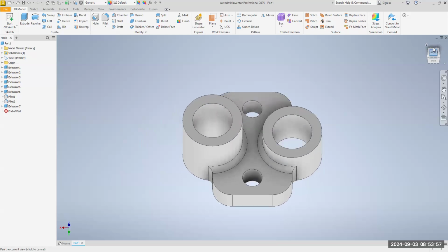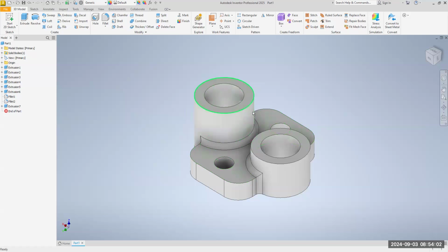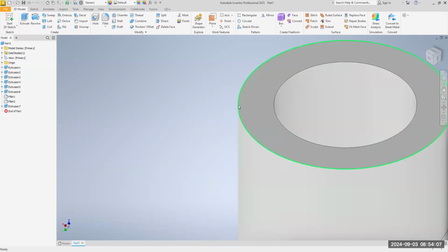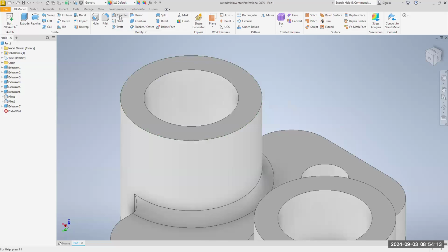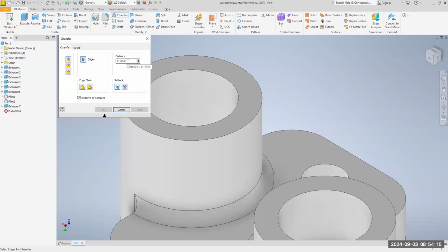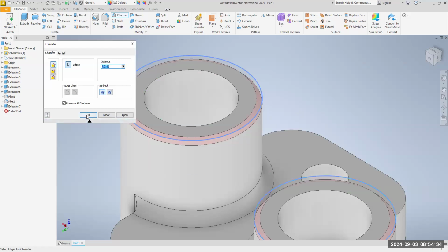We're almost there. Now, I want to put a beveled edge at the top here. Mr. Morris, what is a beveled edge? It is when you're going to put what they call a chamfer. And we're going to go to chamfer, and we're going to make the chamfer distance 0.125 is fine. Oh, let's see. Let's see if we like it. Yeah, that's actually almost too big. Let's make it half of that, 0.0625. And I'm going to click on this one over here as well, and set that.